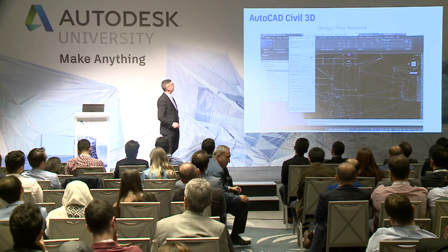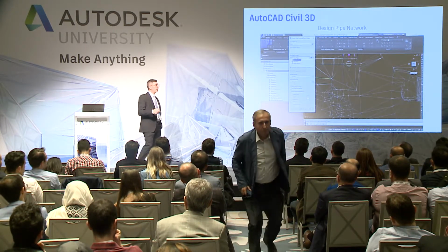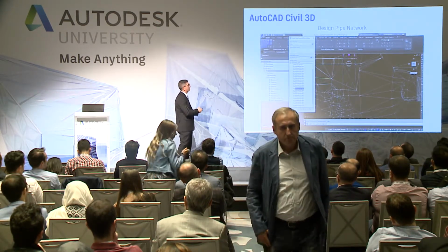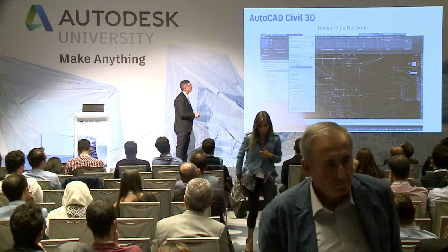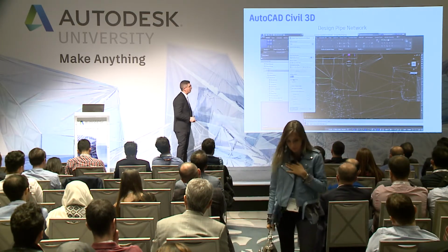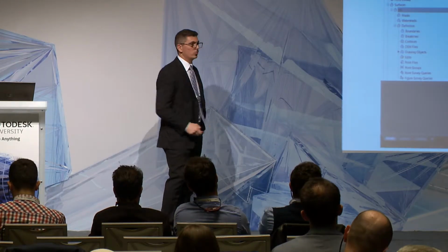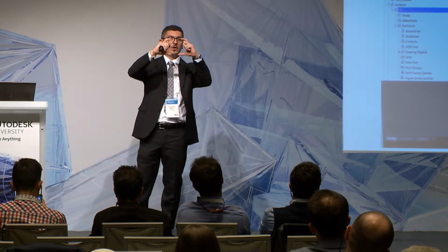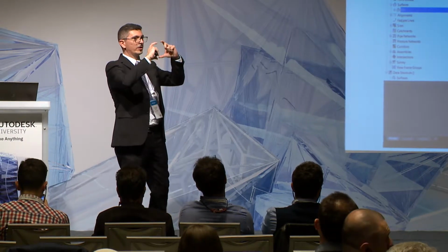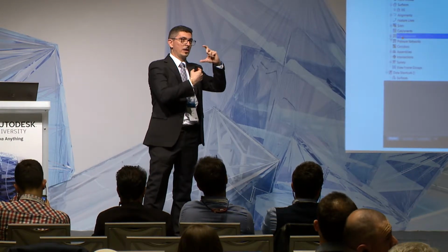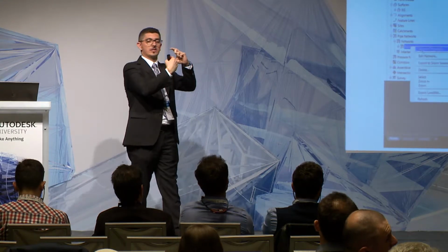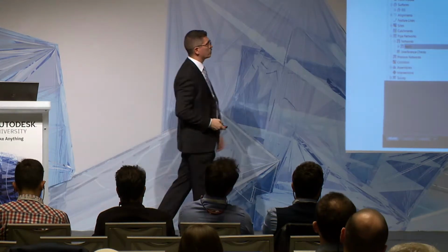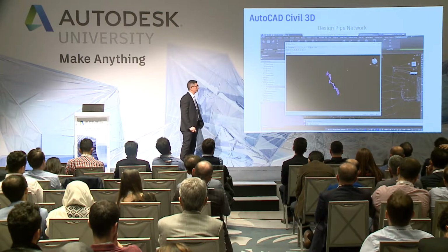Now, one click to convert the element. I can convert the element from the structure to define the structure and to define the diameters of the pipe. And then when I convert, I can select which point of the pipe I want to use for the reference of my grading, of my feature line. It's above, or it's on top, or it's the center of the pipe. When I see this one, the result is this one.